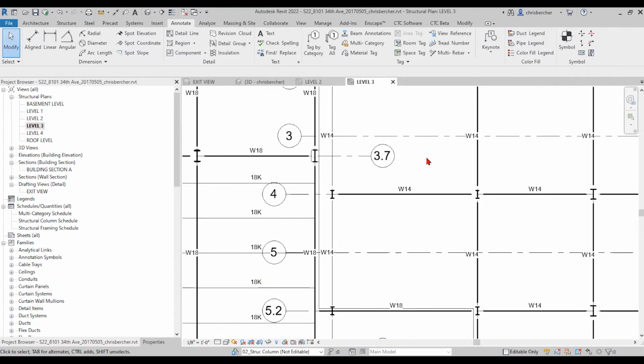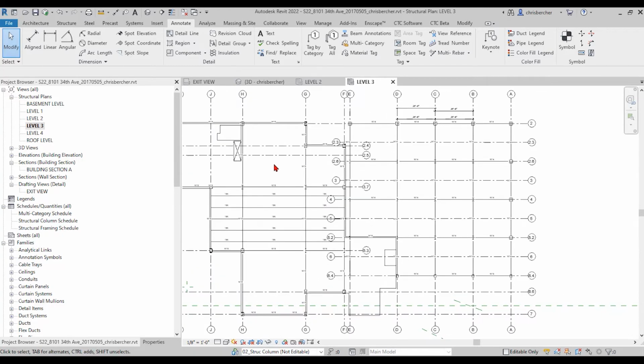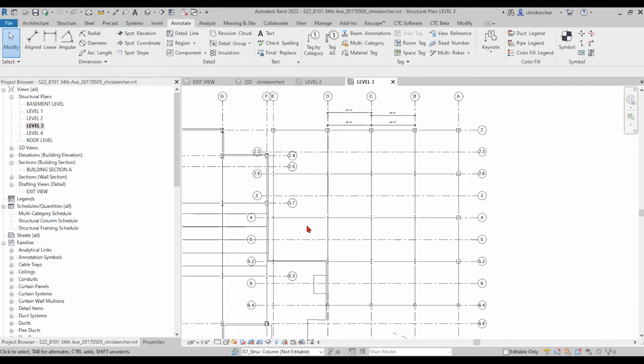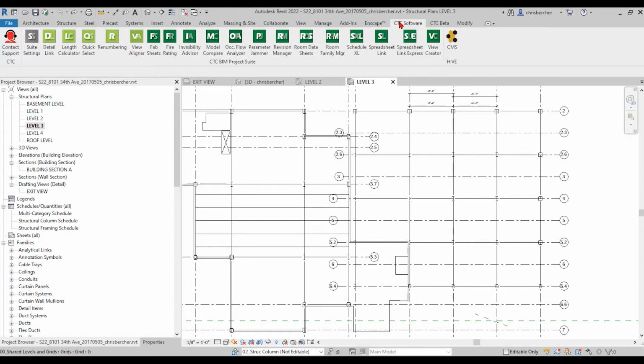So that part worked. Now, the second part to that is the repeatable process, right? So I'm going to quick undo these things real quick, and I'm going to show you now how to do that quickly. Say, pretend this is job 2, right? So I saved that as a settings file before I closed it out. What that allows me to do is load that up and apply the formula back to the model without ever seeing that big Spreadsheet Link window. And that's using a different app called Spreadsheet Link Express.